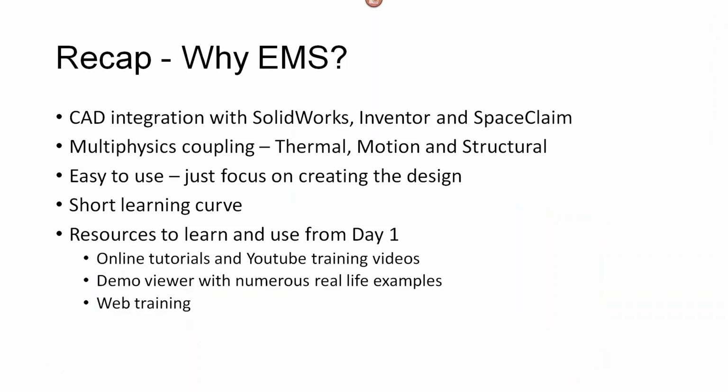Okay. Just as a recap of what we saw about really why EMS, some of the things that I showed you here are probably just described as words. Now, I would say the primary reason for considering a simulation package like EMS would be its very powerful CAD integration. So we saw the integration with SolidWorks, but the same happens with Autodesk Inventor as well as SpaceClaim. So it's well CAD integrated. It also has multiphysics coupling. Today we saw thermal, but there is also motion. If you do any kind of solenoids which have motion, you have motor simulation and so on. We couple it to motion, as well as if you want to do the thermal stresses due to the temperature, we couple it to structural as well.